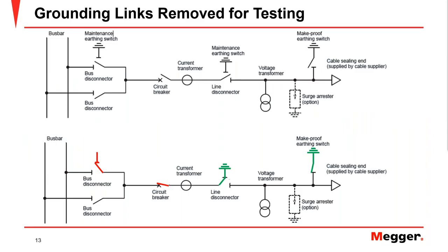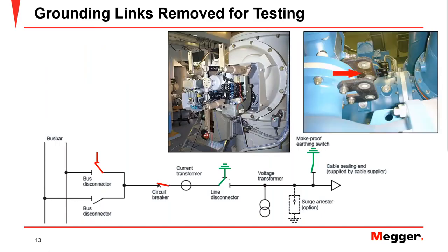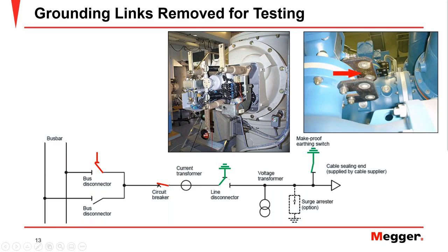To get access to that, what you need to do is remove that bus bar or whatever connection is connecting that primary conductor outside to ground. And when you do that, this is how it looks. In the very first picture that I showed before, everything was connected here diagonally. Now all the links are open. They were left there for purposes of testing.